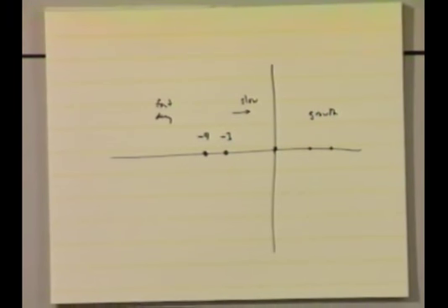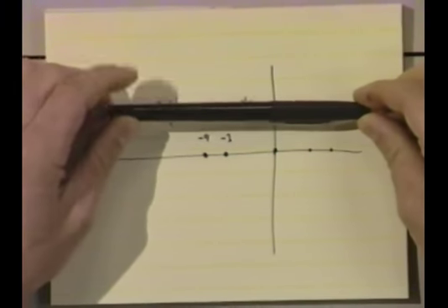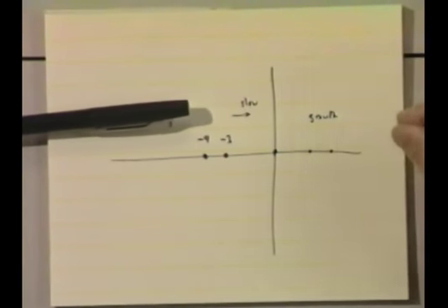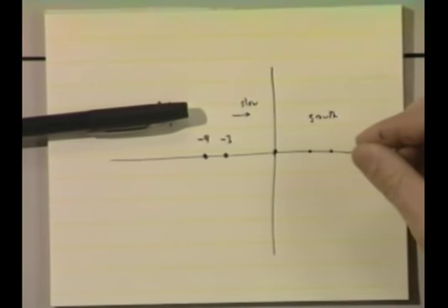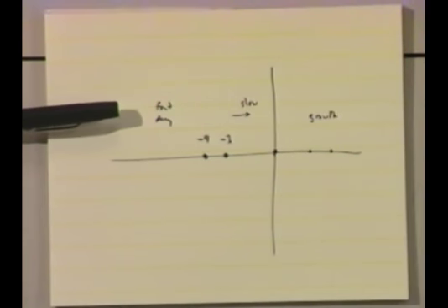So in fact, this is a picture. We're going to go over this many, many times, but this is going to be about 2 or 3 pictures that the whole class is going to be based on. This is one of them. So from now on in the complex plane, as you move left and right, and we're talking about the roots of the characteristic polynomial, as we move left and right, what it means is growth or decay rate from now on. Things way to the left here, very small real parts, negative real parts, those correspond to rapid decay.